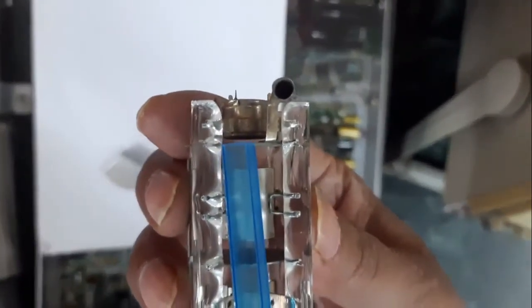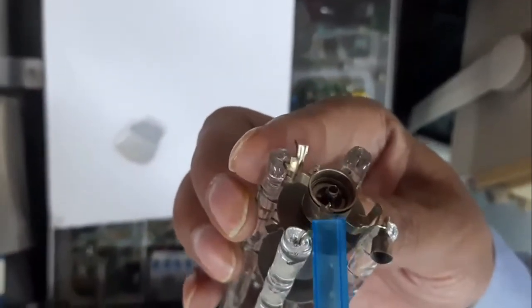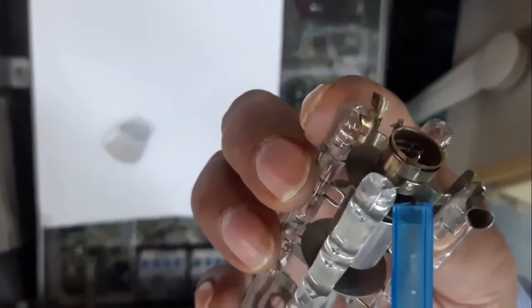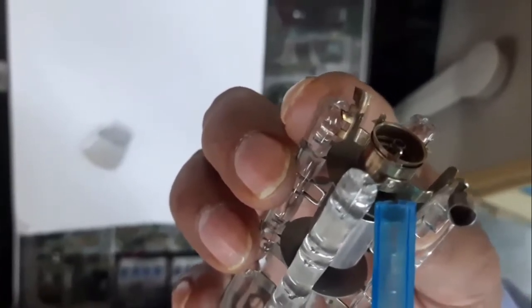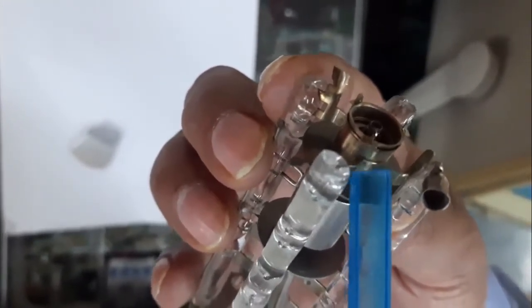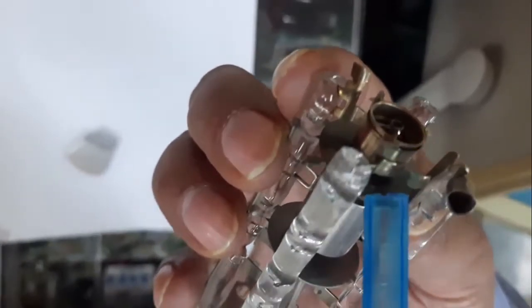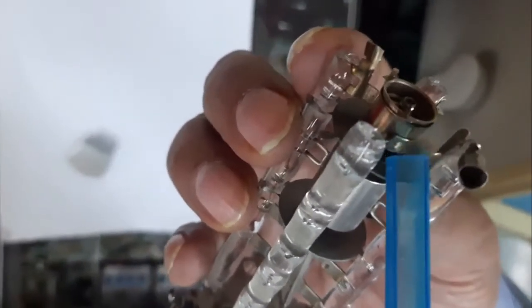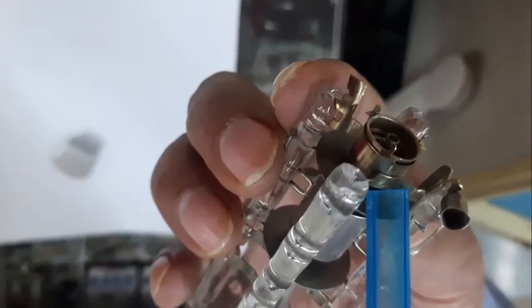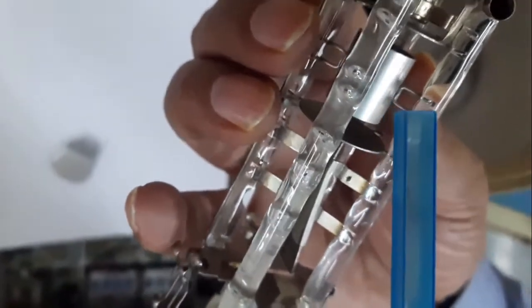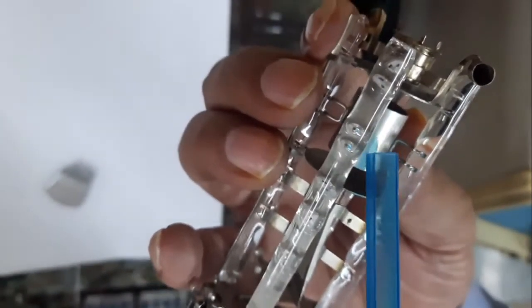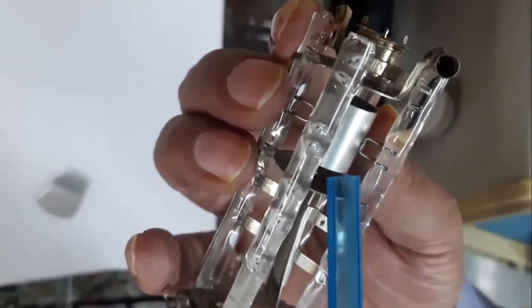This is the circular plate here, having certain drills inside it for making the different electron beams. Here, the section where I am indicating is the indirectly heated cathode, rated at 6.3 volt. And what is the role of the indirectly heated cathode? The cathode is deposited with strontium and barium oxide, so that must be protected from the high temperature, and that's why this is an indirectly heated cathode. Then you have a cylinder, and that cylinder was used for the focusing purpose earlier.